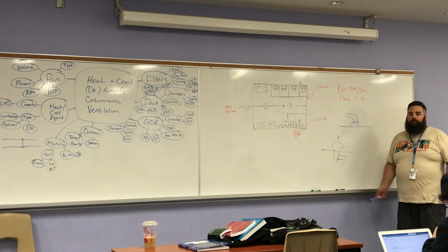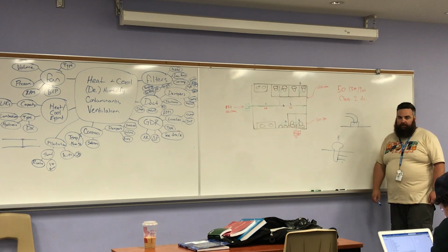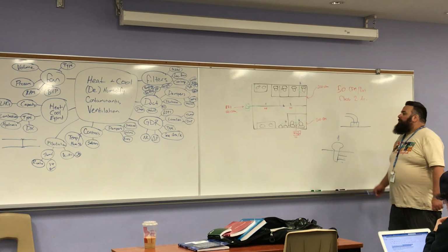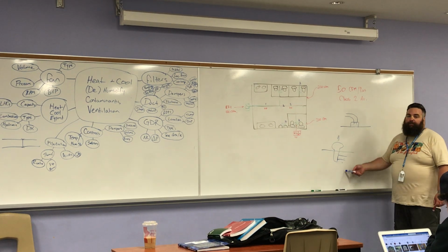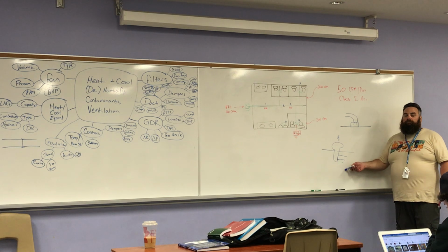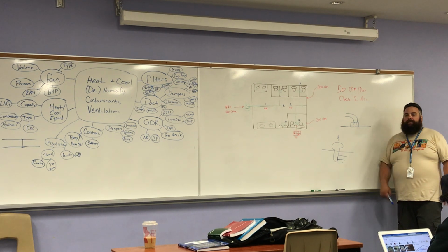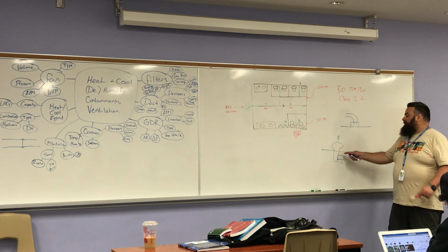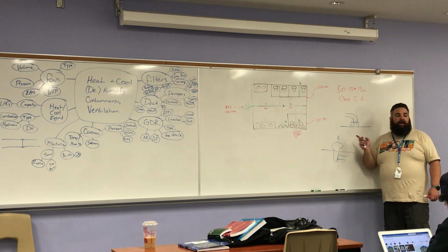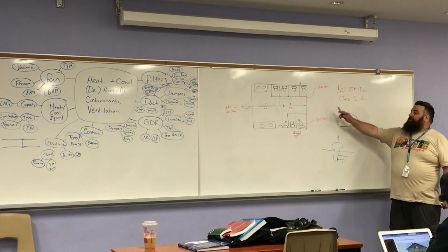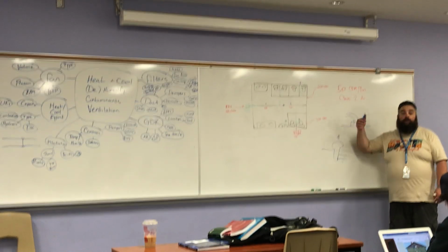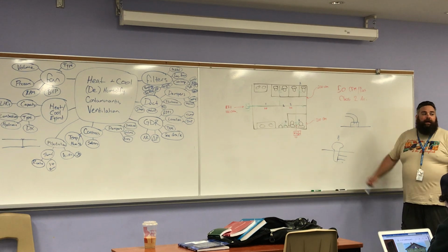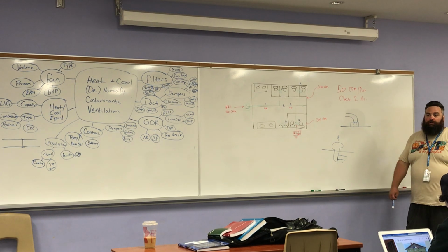We have to know that, we have to decide that, okay? We have to communicate that to the installers. So there's another pressure drop here. What about a flex connector? I might want a flex connector there because that fan's going to vibrate. I don't want to transfer that vibration to my ducts, because that'll be annoying if you hear a rattling while you're trying to use the bathroom. So I'll have a flex connector. That has an additional pressure drop.